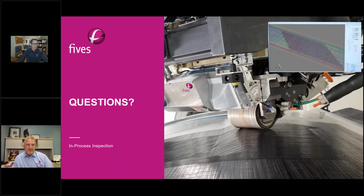Yeah, and a splice is a good example, right? We know a splice is 2 layers of tow that are stacked up on each other. And we typically like to have at least the thickness of 1 tow to be able to identify it. But every FOD condition is somewhat unique, right? What we can do is set up all the different examples and just run tests. There's a large collection of FOD that we'll see. But we all know that seeing submicron FOD is difficult for any sensor.